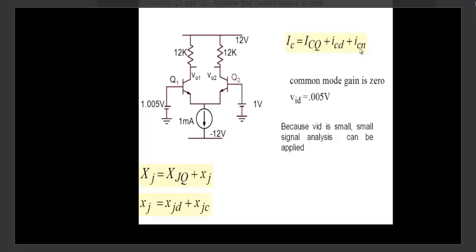So small signal analysis is out, and we'll see how to handle those cases here. Anyway, so IC1, because note that 1 milliampere will divide into 0.5 and 0.5 here. So 0.5 milliamperes is the bias point, and I have only the differential part here. And in the differential part, please recall, this point will become ground. Okay, and what is the differential signal that appears here?